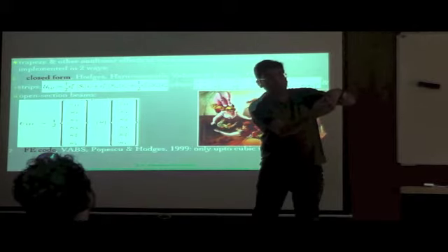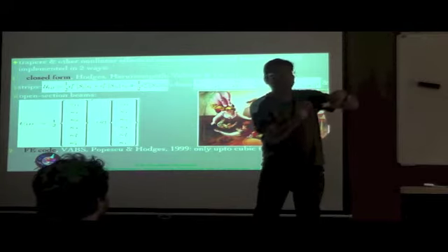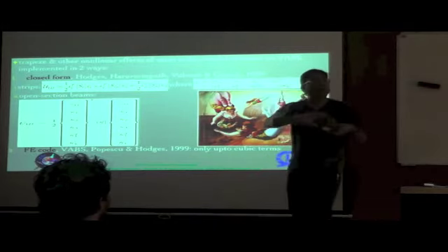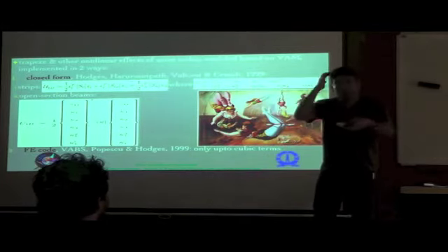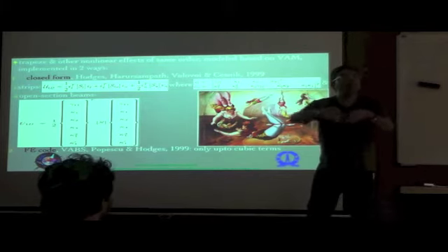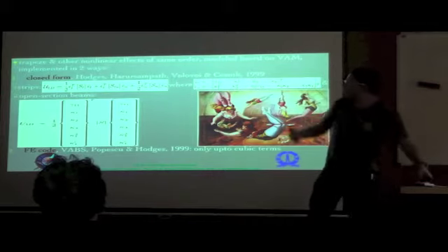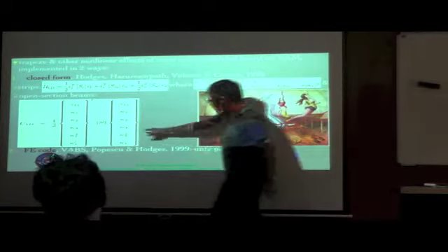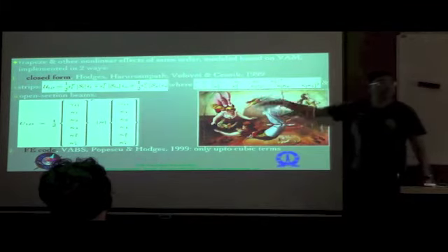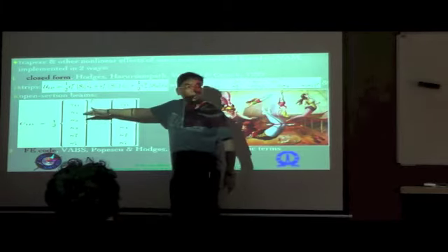In other words, in each one of these, the moment arm is of the order of magnitude of the thickness rather than of the cross-sectional dimension, and that's the reason why you have it torsionally soft, and therefore the torsional stiffness is low, and therefore kappa 1 can be much larger compared to kappa 2 and kappa 3, and therefore a nonlinearity associated with kappa 1 is present, whereas the other nonlinearities have all disappeared in an open cross section when you go from a strip to an open cross section.